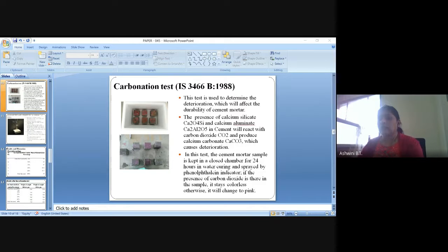The flow mortar reading, that is the measurement of the workability, started for the river sand at 20 mm. For 10% replacement, it is 55, 20% replacement, it is 65, 30% it is 67.5, and 40%, 69.2, 100% is 73.